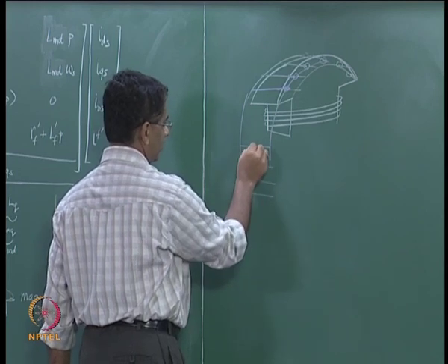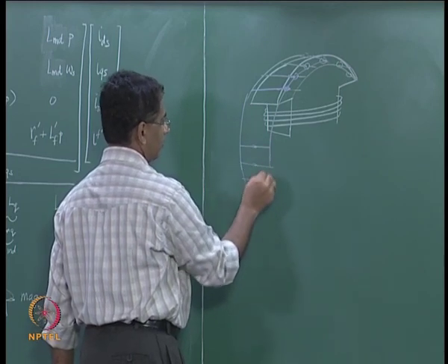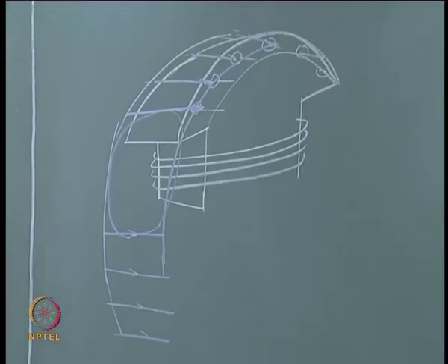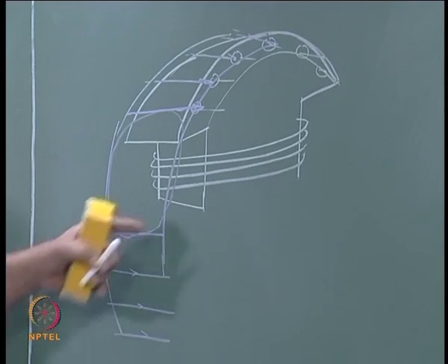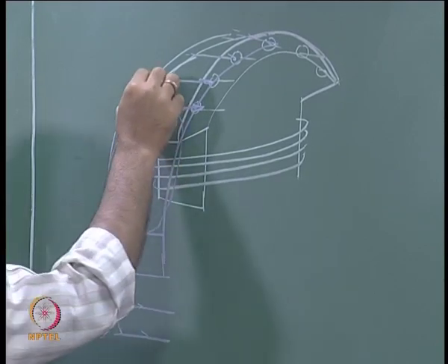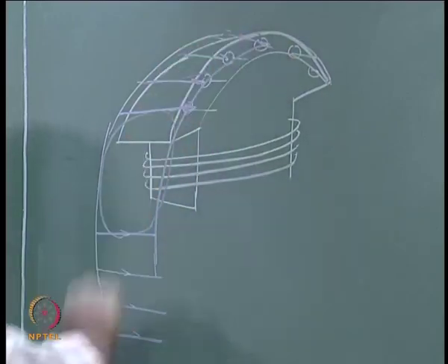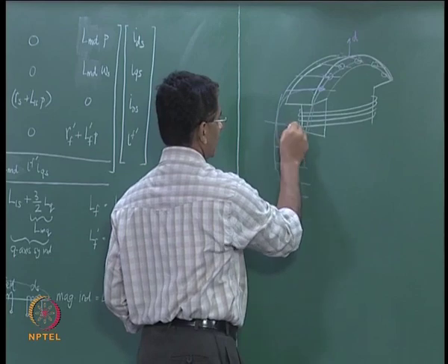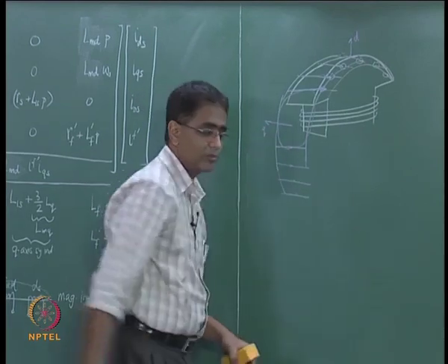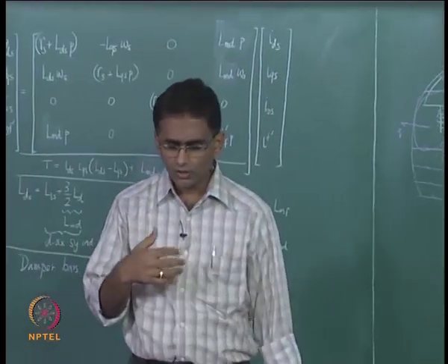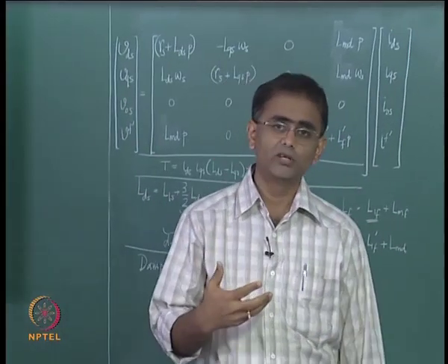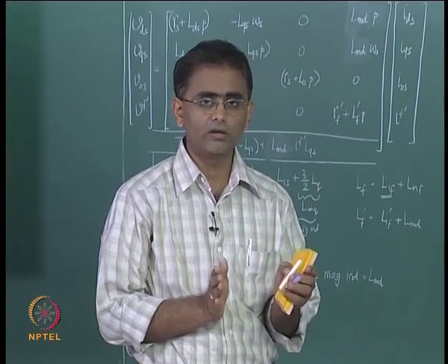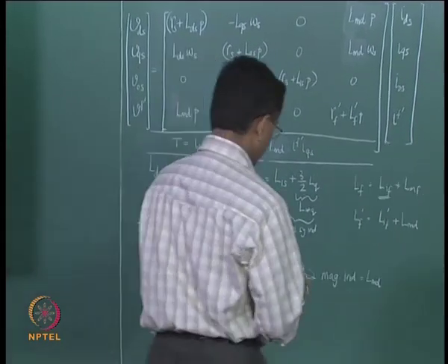So, there is going to be flow of currents all around, and this causes the loop that thereby forms here causes a source of excitation along the Q axis, and definitely there are loops formed here which cause a source of excitation along the D axis, and therefore because damper bars are there, it will affect the machine model by providing sources of excitation both along D and Q, and therefore that is represented as follows.